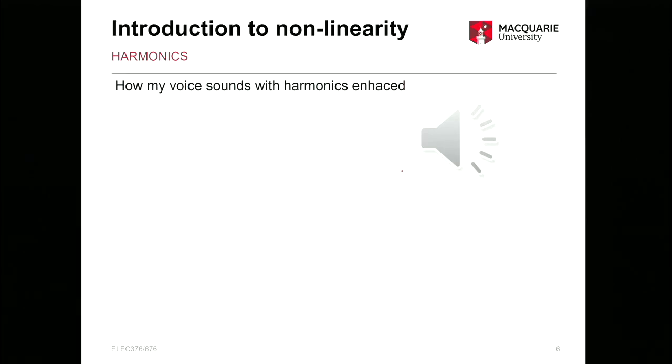So the human voice is between 20 hertz and, for a male voice, somewhere around 2500 hertz. And so this amplifier is designed for a human voice. If I play a violin here, which contains a lot of frequencies beyond human speech, maybe this amplifier system is not designed for that.